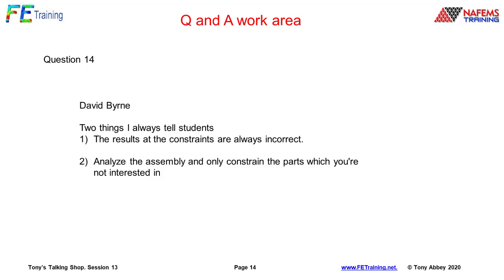We actually had a case about 15 years ago where prime contractors were basically modeling like half the ship because of exactly that point. Let's connect that deck to that deck to that deck. We had huge models asking for 5,000 modes. So it's a good idea, but I think you must be careful not to go too far in that. But generally, yes, that's another way of doing it, is to actually model the surrounding structure in there.